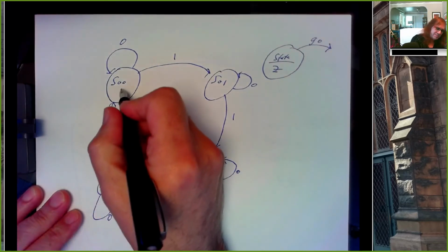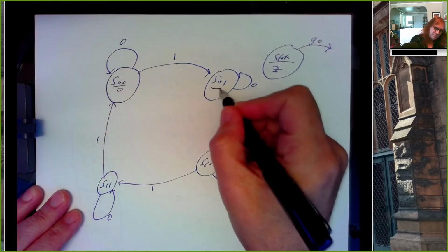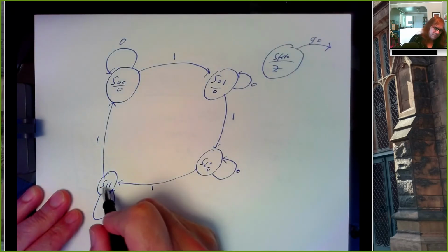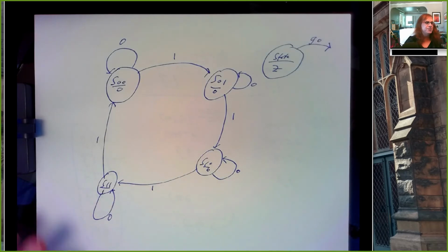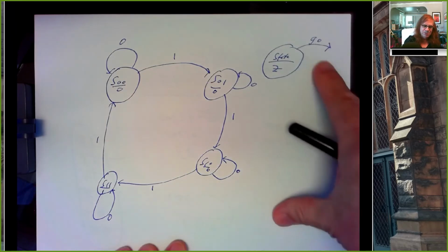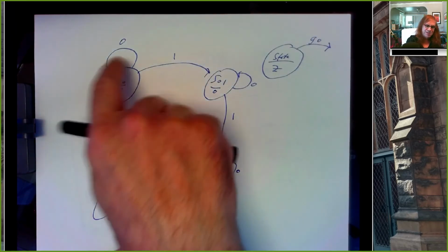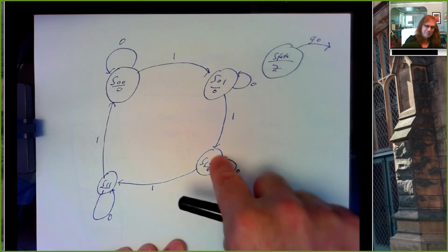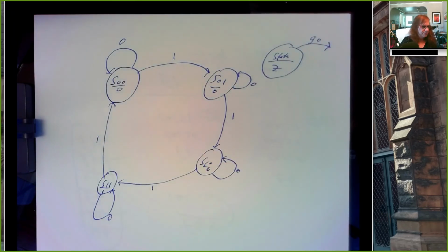And I'll just set my output to be a 1 when I hit state 3. So this is an up counter that can be paused. If go is equal to 1, I'll move from state to state. If go is equal to 0, I'll stay in whatever state I'm in.